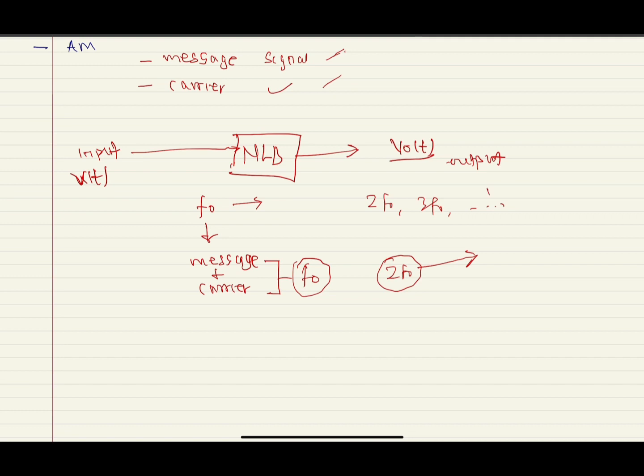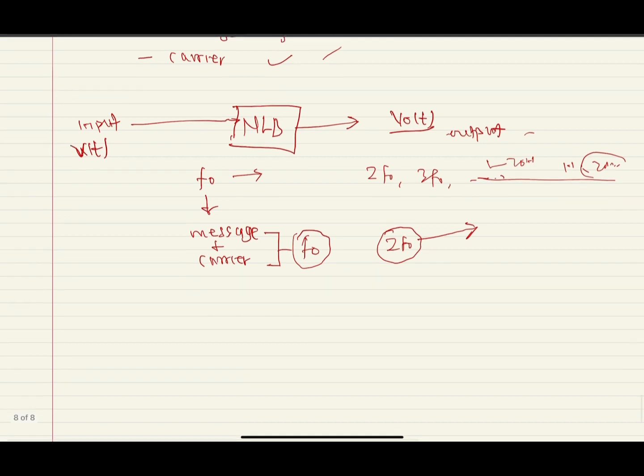So if your low frequency is 20 Hz and your high frequency is 20 kilohertz, we can generate cutoff frequencies from this, and then use them to design our bandpass filter in such a way that it will attenuate whatever frequency or noise the nonlinear device brings into the system, either low frequency or high frequency, due to the harmonic nature of the device.